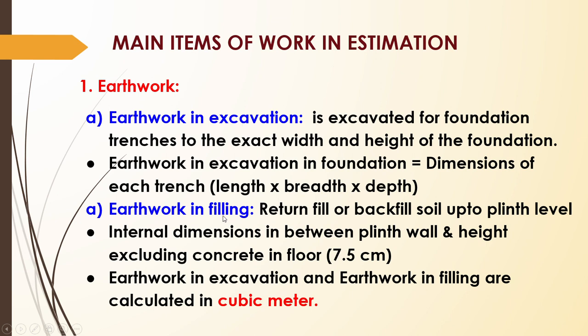Now what is this earthwork in filling? Earthwork in filling is nothing but after making the foundation, we will fill the foundation with soil up to the plinth level. So plinth you all know, right? Plinth is nothing but the exposed surface of the foundation. So up to the plinth level, we will fill the foundation with soil. That is known as earthwork in filling. So in the first case, we were taking out the soil. In the second case, we are filling the soil.